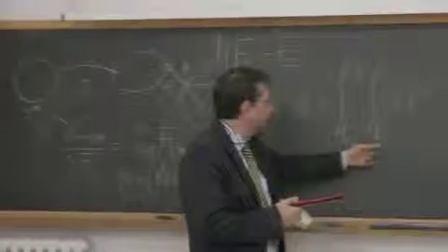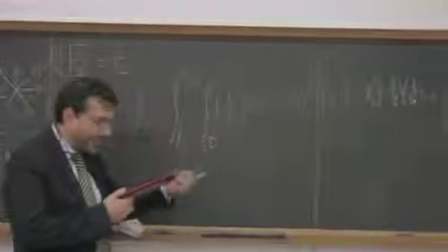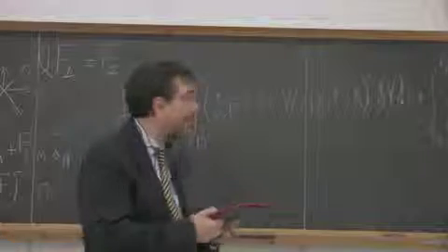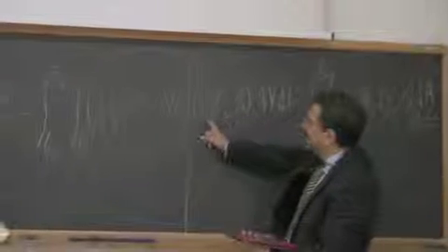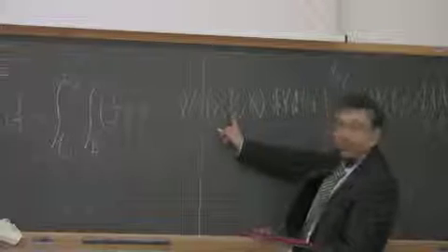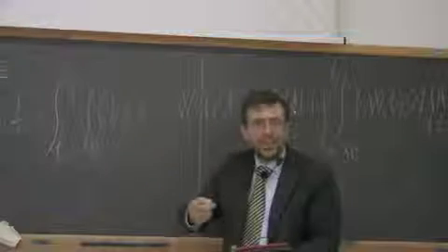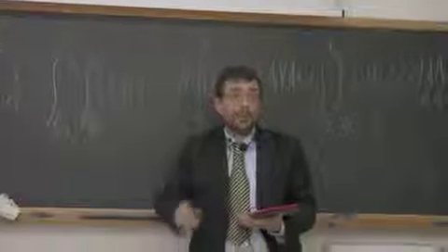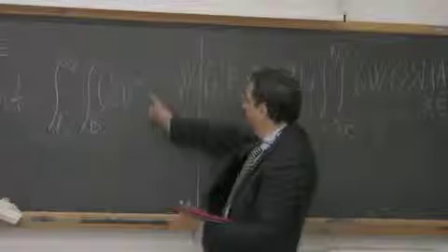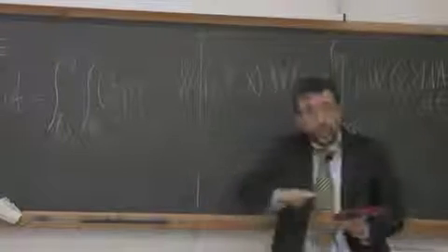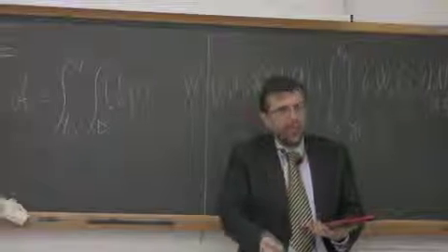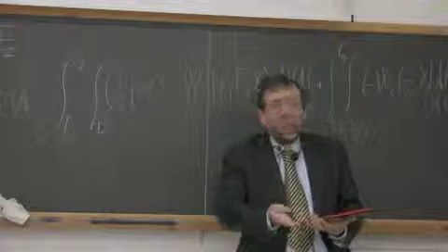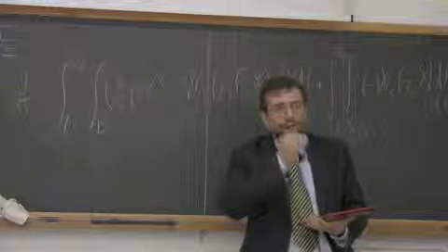This is a four-dimensional space, so you have a variable time and three variables of space. You can remark this: F is the derivative of chi with respect to space. V is the derivative of chi with respect to time. So V and F all together are constructing the four-dimensional gradient of chi. This is the source of every difficulty.